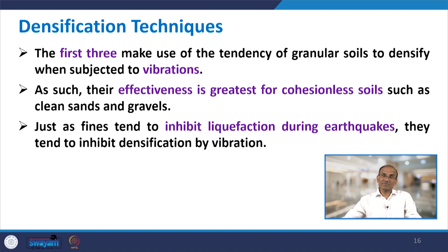In case of cohesionless soils, as fines tend to inhibit liquefaction during earthquakes, they also tend to inhibit densification by vibrations. So, if fines are present inside the soil, they will try to resist the densification. They also decrease the liquefaction resistance. In the same way they also inhibit densification due to vibration.